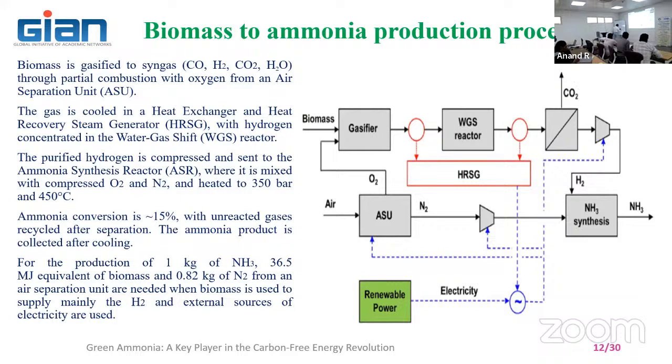If you take the gas from the bottom, it's called downdraft gasification. If you take the gas at the top, it's called updraft gasification. If you take the gas exactly at the center, maybe you can call it crossdraft gasification. Ultimately, the gasification system is used to produce gas to the maximum, but I am not going to get only 100% gas; I will get some percentage of liquid and some percentage of solids also.